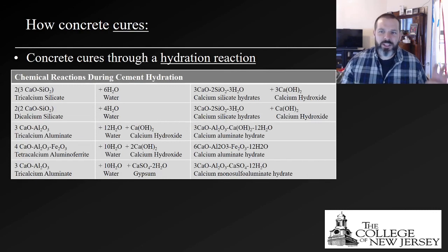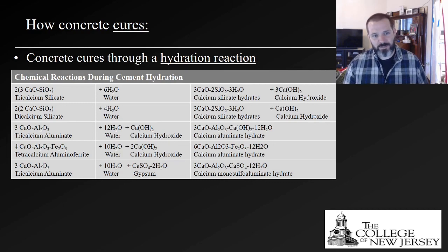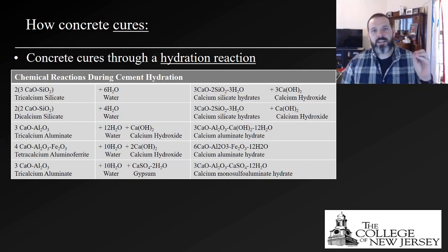Now, the important thing for you to remember is that concrete does not dry. Concrete cures. Drying is the removal of water. Curing is a chemical reaction. So, Portland cement is formulated to fuel this hydration reaction and make it as efficient as possible.